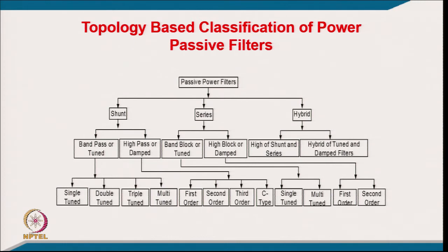Coming to the series passive filter, which we discussed, of course the shunt passive filters, because they are normally tuned for higher order frequency, at fundamental frequency behave as a capacitive network, and they generate capacitive reactive power. In general, a circuit like a thyristor converter requires reactive power of leading nature, because they generate reactive power of lagging nature. So, it fortunately matches the requirement of such applications, and passive shunt filters have been in practice since long, since HVDC appeared in 1954 or so.